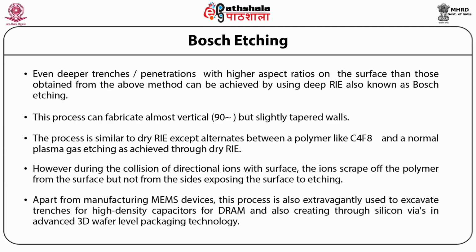Apart from manufacturing MEMS devices, this process is also extensively used to excavate trenches for high-density capacitors for DRAM and also creating through silicon vias in advanced 3D wafer level packaging technology.